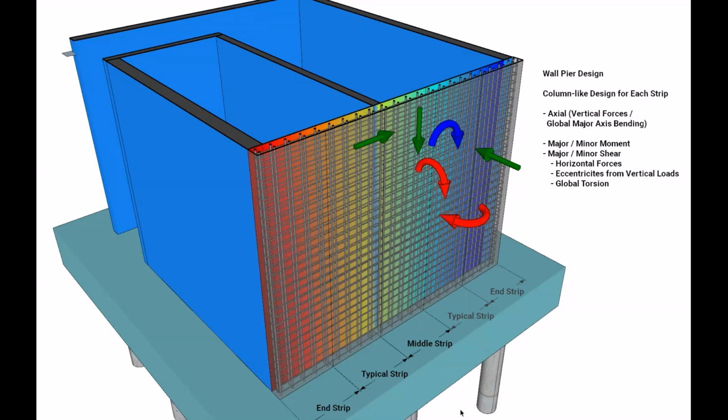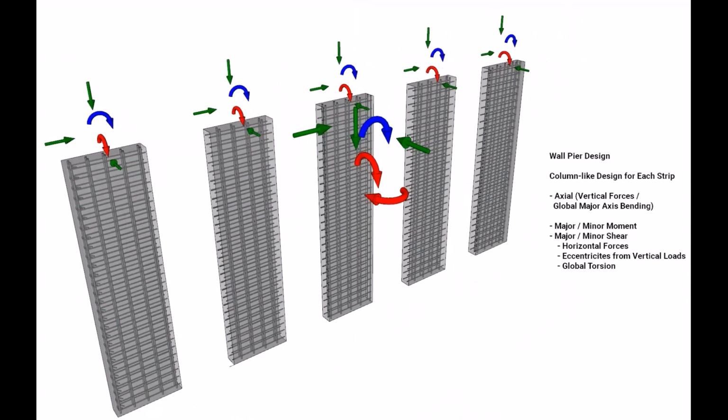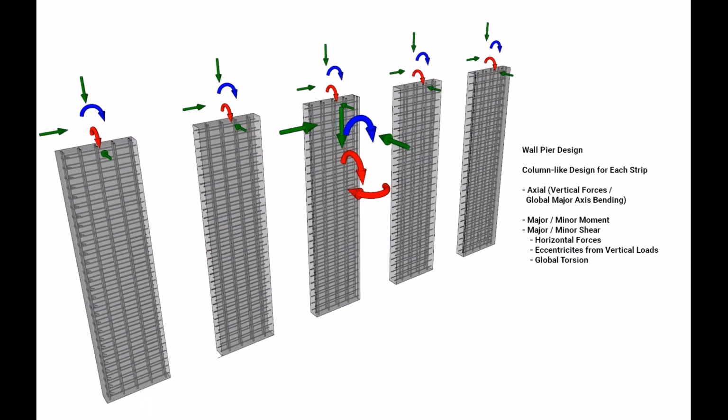And if we explode this up, we can then look at each of these as individual strips, with their global loads being distributed or allocated across each of the strips accordingly. MasterSeries then can carry out the design for each strip, taking into account all the above, and the breakdown of these checks is denoted quite clearly on the design output. Again, it's worth paying attention to the restraint conditions for each panel, as this will be another manual entry, critical for your design.